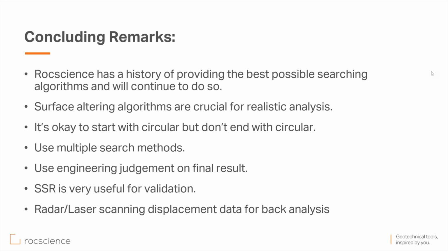If they can't take tension and you allow tension to occur on the base, the tension can have a very adverse effect on the factor of safety. If that tension is near the toe, it can give you a fictitiously low factor of safety. If it's near the crest, it can give you a fictitiously high factor of safety. So a lot of people understand that we should be using tension cracks and things like that, but make sure that you look at the stresses on the base.